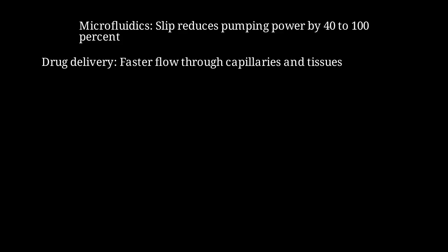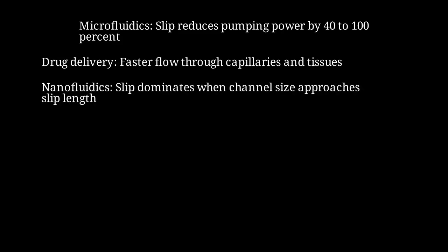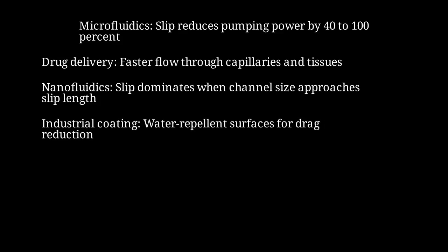Let's talk about why this slip flow phenomenon matters in real-world applications. In microfluidic devices, slip flow can reduce the required pumping power by anywhere from 40 to 100%. This is huge for portable diagnostic devices. In drug delivery, understanding slip can help us design better systems for transporting medication through narrow capillaries and tissue channels. In nanofluidics, when the channel dimensions approach the slip length, slip effects completely dominate the flow behavior. In industrial applications, superhydrophobic coatings can reduce drag on ships and pipelines, potentially saving enormous amounts of energy.